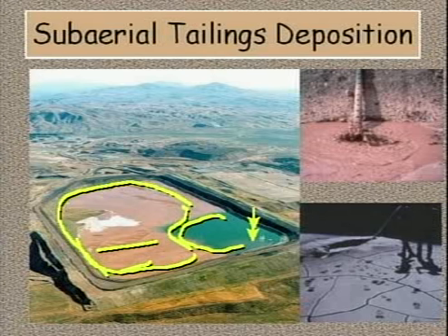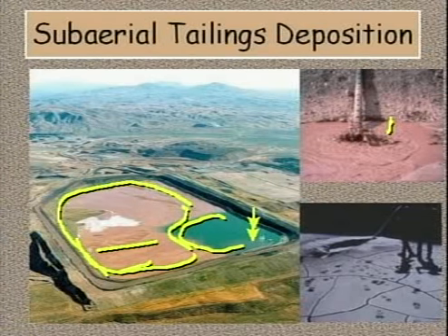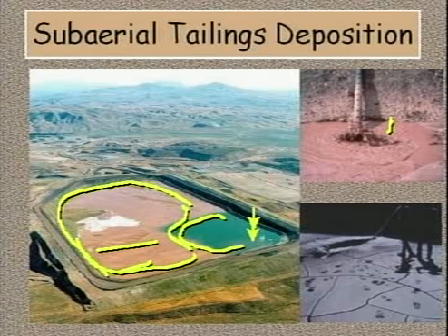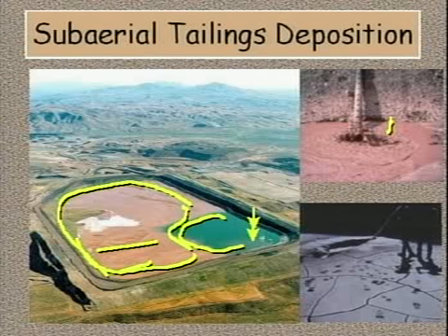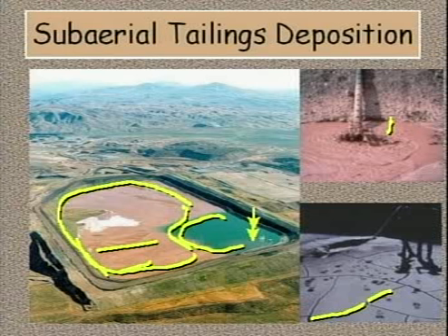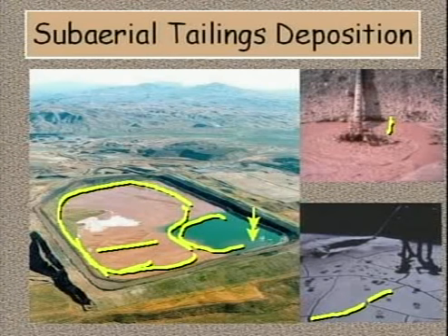The tailings are placed through drop bars, which are right here, which basically dissipate the energy out of the tailings slurry, and it's deposited in this thin lift. And after a specific deposition zone is completed, and this zone actually dries out, tension cracks form. As you can see in this part of the slide here, these tension cracks form, and the solids are dense enough to walk on. And this can occur within a week after deposition stops because we put it down in thin lifts.